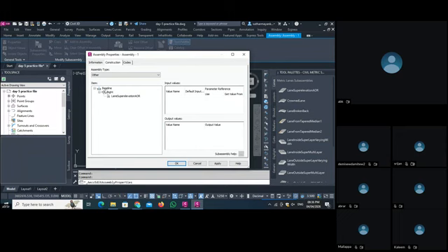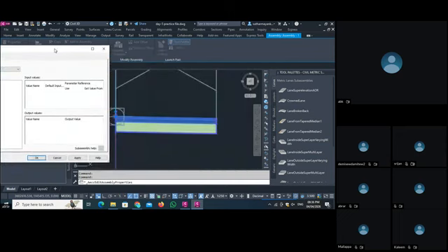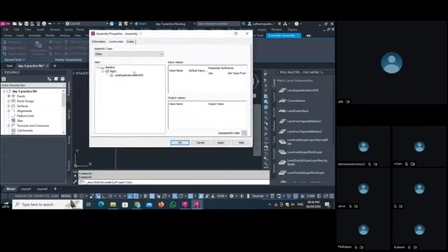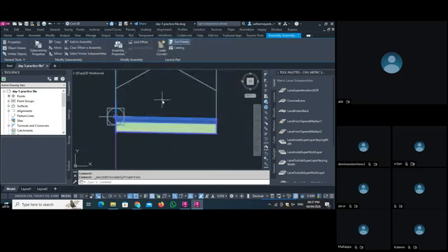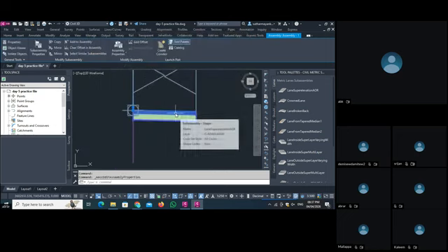So you see all the workflow. First of all, we have a baseline. You can see the baseline. Then this is the right side, and at the right side we gave a lane. So you see the workflow here. If you want to change anything, you can change it from here also. You can change the volume. If you want to use this layer or not, you can keep it, or you can select this whole part from here also. So this is the basic thing to understand before starting the sub assembly part.